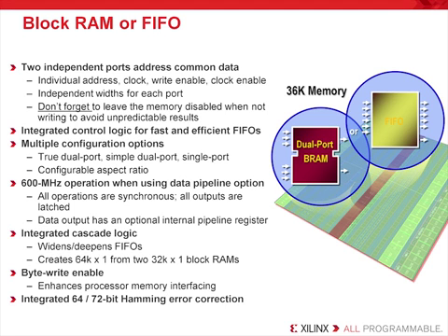As I mentioned earlier, you can load the block memory's contents during configuration with the FPGA bitstream, so if you reset the memory while it is running, you only clear the registers, not the contents of the block RAM.